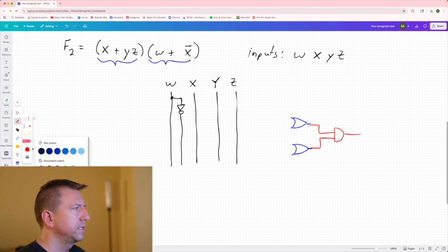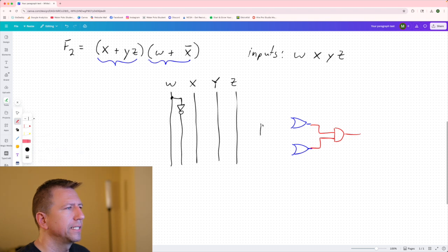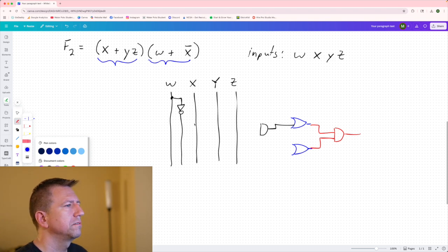All right, so here is where I threw you a little bit of a curveball, because this isn't a literal. This is actually another term, and it's an AND term between Y and Z. And so we have a fourth section here, if you will, these intermediate ANDs and ORs that might happen. And so I'm just going to draw an AND gate right here, and that AND gate will feed into our first OR gate, like so. So now I'm going to connect everything. I'm just going to use a blue color here for all these connections. Maybe no, you know what, I'll use black.